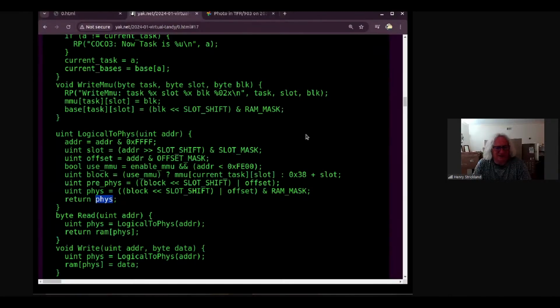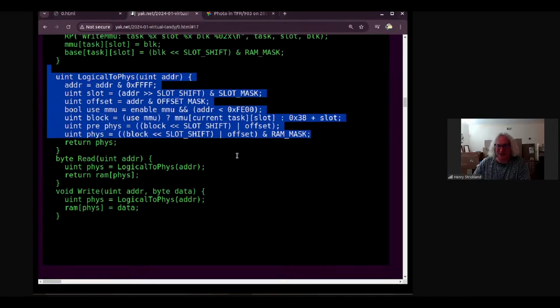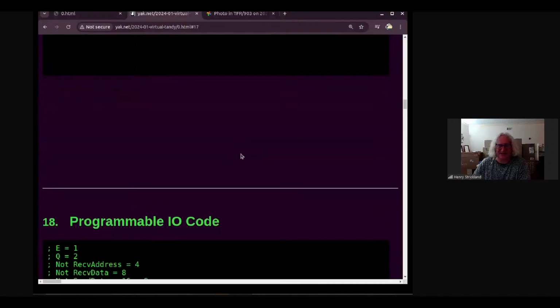Let Mark Siegel ask questions if he's got more questions about that. But you can see that executing this code on every read cycle or every write cycle, that's a lot more code to execute on the ARM core inside the C code inside the Pico. And that has to be executed before the results are sent back to the 6309 CPU, and that delays things a bit.